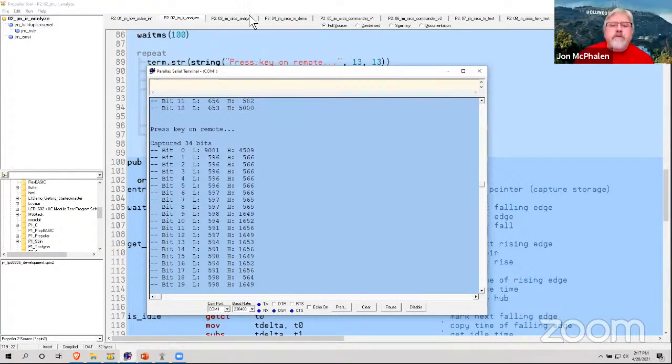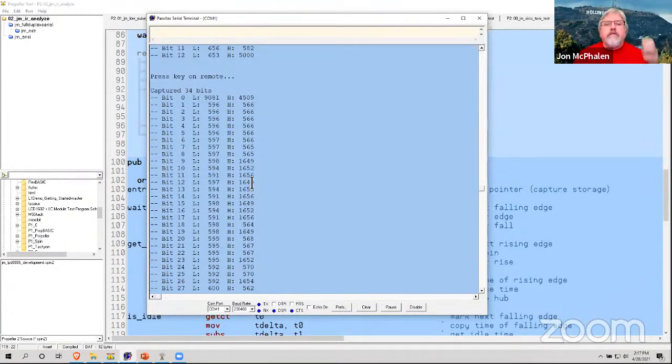So I'm sorry, I wasn't terribly clear. The reason for this program too is so you can figure out what's going on with your remote. I mean, later, if people are interested, there's another protocol from Philips called RC5 and a derivative called RC6. It uses different bit timing. I suspect that that's what this is, RC5. I'd have to go look at it.